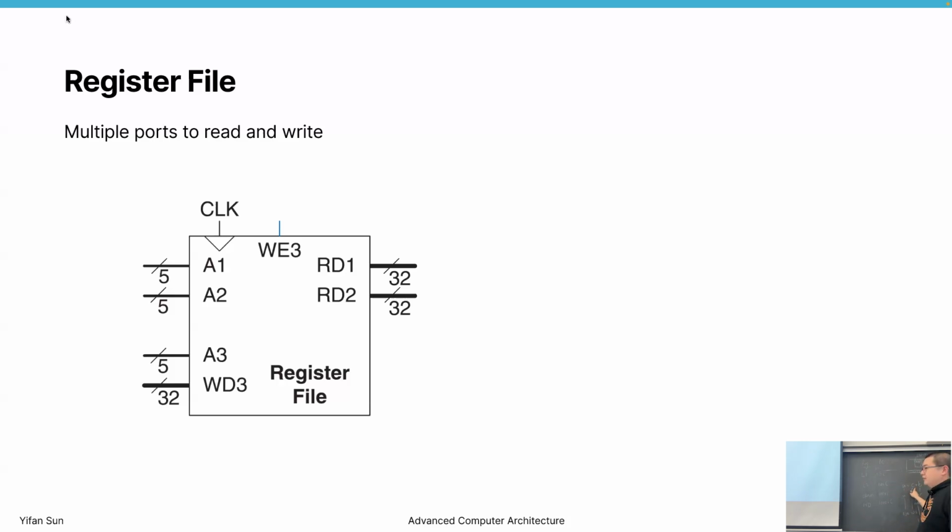Although, actually, when we talk about pipeline execution, in 1 cycle we are probably writing something from before, from the previous instructions. Later on, when we read the data, we read for a later instruction, and it will pass a few stages to calculate a result. And then the result will go back to the write stage. Now we'll write the data into the register file. It's a later time, but overall we want a 2-to-1 ratio for read and write. It's a typical consideration for register file design.